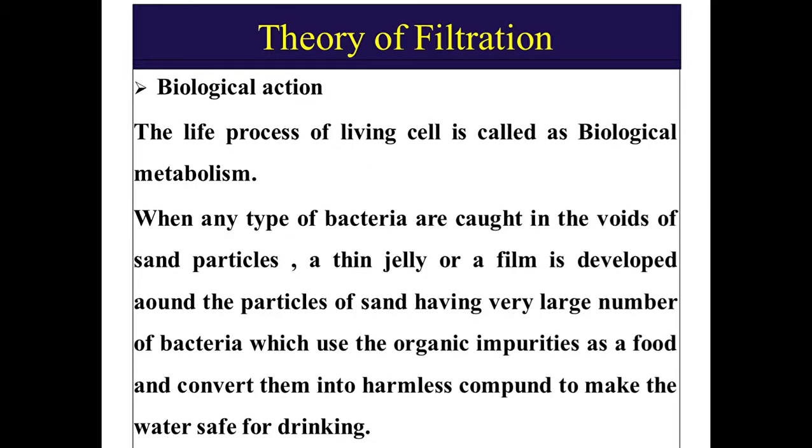Third is biological action. The life process of a living thing is called biological metabolism. When any type of bacteria are caught in the voids of the sand particles, a thin jelly or film is developed around the particles of the sand, having a very large number of bacteria which use the organic impurities as food and convert them into harmless compounds to make the water safe for drinking.